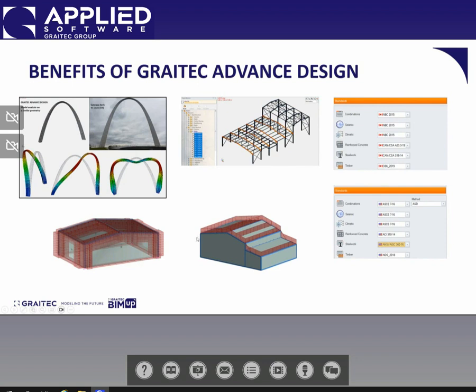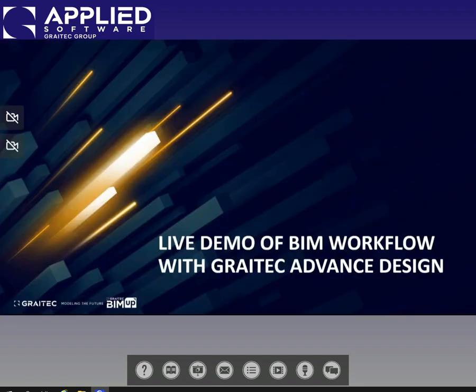And here at the bottom, I have 2 screenshots from the automatic snow load generator, and as well the wind load generator on those structures. So all of those loads will be generated automatically. And you also have the option to manually check them to verify them. And in case you want to change the value or the quantity of that load in Advanced Design, you have the option to modify those. So it's a very flexible workflow and set of tools that we have in Advanced Design.